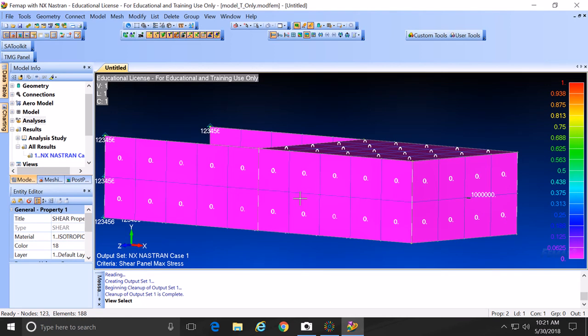Which I was kind of expecting, okay? I'll tell you now why. It's because basically the shear panels need to be deformed. And if you put it in the middle, this is not being deformed. Let's first try the other way. Hopefully it would work. So over here, if you want all results, just click on it and delete it.